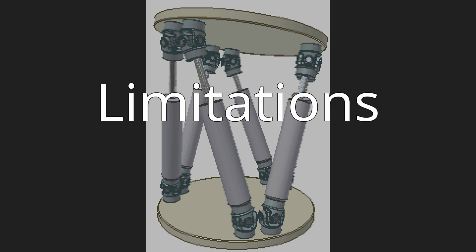Potential sources of false cues are software or hardware limiting. When the simulator approaches a displacement limit, two methods of protection are provided: one, software limiting, and two, hardware limiting. In either case, the simulator is decelerated to prevent damage to the motion system. Large false cues are often associated with this deceleration. Return to neutral: this false cue is attributed to the overshoot of the high-pass filters to step-type inputs.